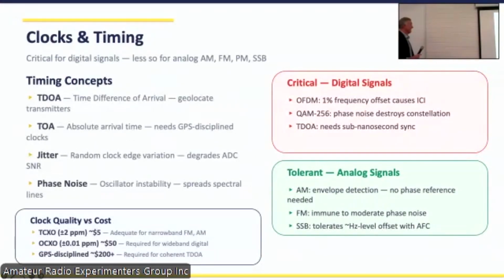Clocks. As we look at the signal conversion from analog to digital, timing is so important. If we have movement in time, then we start to get quantized noise coming into our signal. The big advantage with digital is once it's converted, it doesn't have noise added to it. In the analog world, every time we do something with a signal, it adds noise. In the digital world, as long as it's the same quantized size and we're not changing the data itself in any major way, it doesn't add noise. It allows us to do all that processing without adding noise to it.